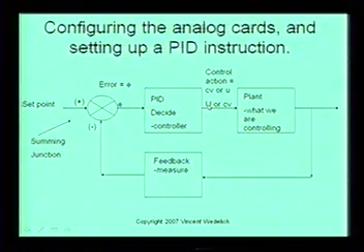So we're going to open the valve more to fill the tank up more to compensate for this change in usage in this case. So if the usage is dropped, so the tank would start filling back up, right? So it'd start increasing in level, and that would come back here and say, oh, no, wait, I'm above the set point now. So now this becomes a negative error, and then this guy says, okay, let's change this and start closing the valve so the tank drops down, and decreases back down to your desired set point level.